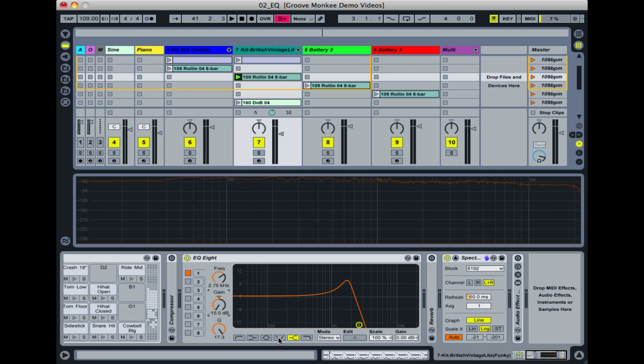And the final filter type we're going to have a look at is the notch filter. Now, a lot of EQs might not have one of these, but it's particularly useful for notching out a specific band of frequencies, sometimes very narrow. So it could be useful for cutting out things like hum. So maybe if your recording has a bit of mains hum in it, then you can try notching out at around 60 Hz or 50 Hz, depending on where you live.